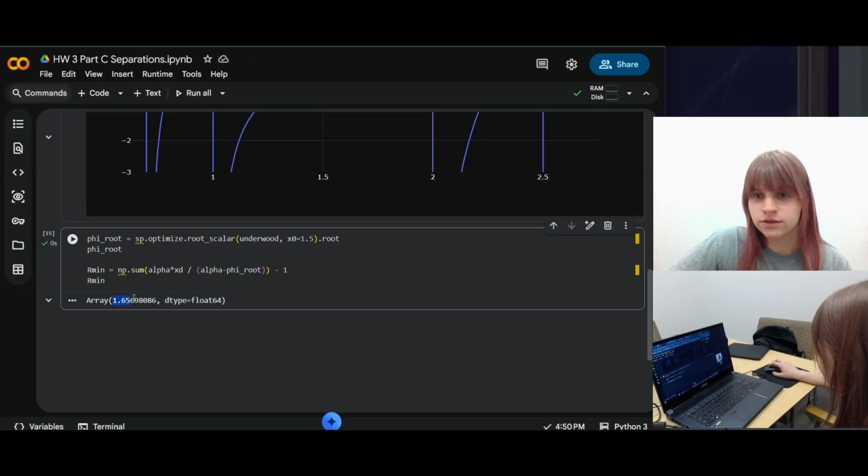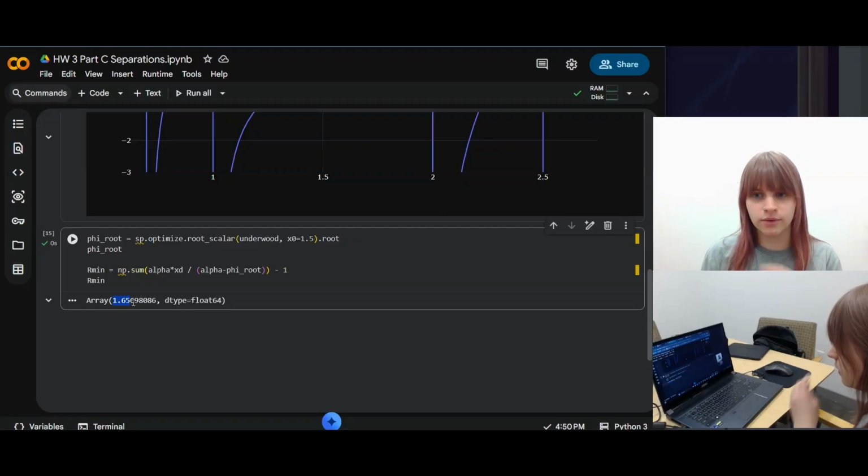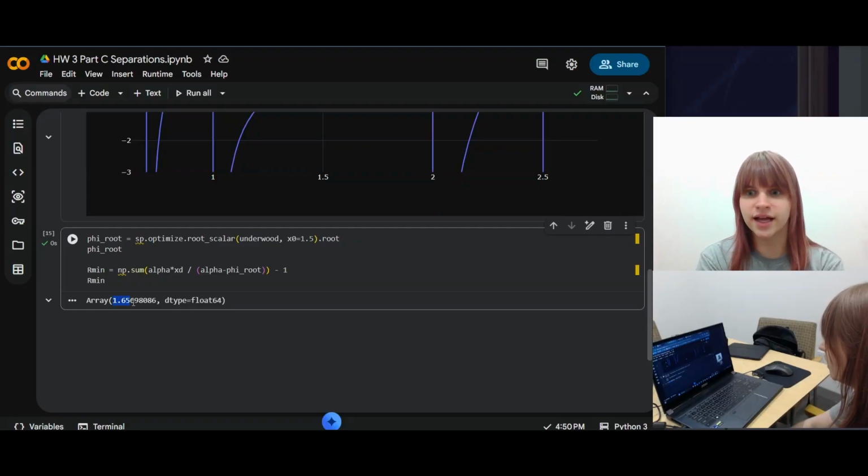1.66. So basically what that means is if we use any reflux ratio less than about that, we're going to see that pinch, and then the reflux ratio isn't high enough, so our purity will suffer, and everything will suffer. Our column will not behave as we want it to get the purity or recovery, etc. that we want. But obviously you can go above that ratio, just not below.